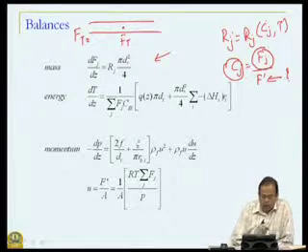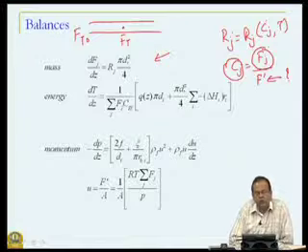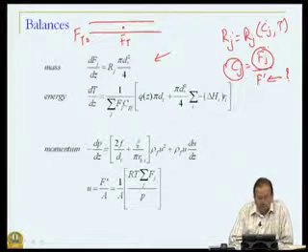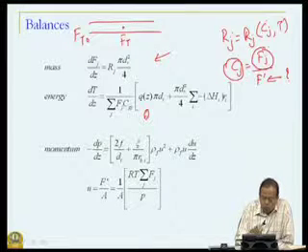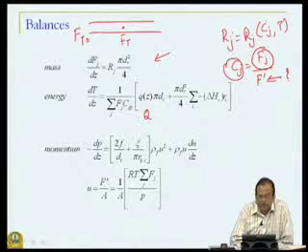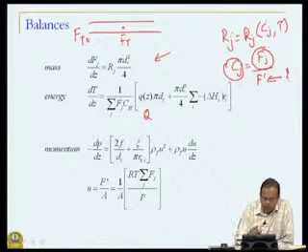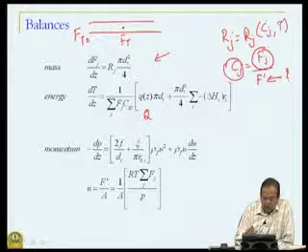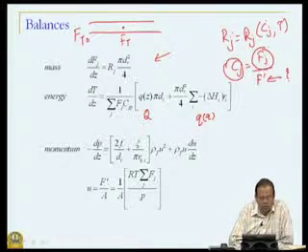Okay. Second is the energy balance. Energy balance also is the same as the energy balance for a tubular reactor, except the term Q that was there, that is the heat added to the system, is now represented in terms of the flux Q of Z, that is, the heat flux of those burners at various different locations.